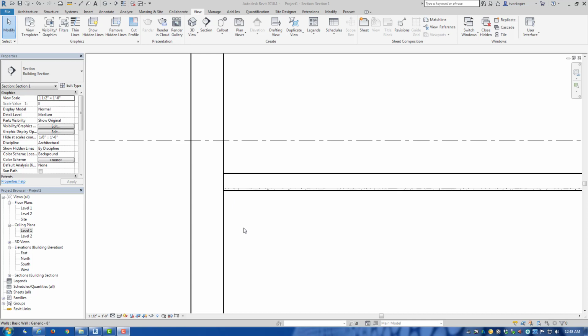I recommend this mainly because the lighting or the lights in Revit are attached to the ceiling, and so you need to create a ceiling by itself for the lights to attach themselves to. So you cannot create a gypboard ceiling as part of the floor assembly and have the lights in Revit attached to it. So quickly, let's take a look at how we might do that.